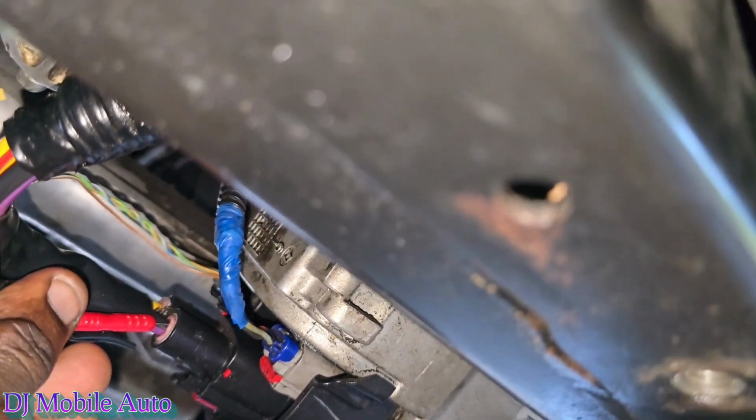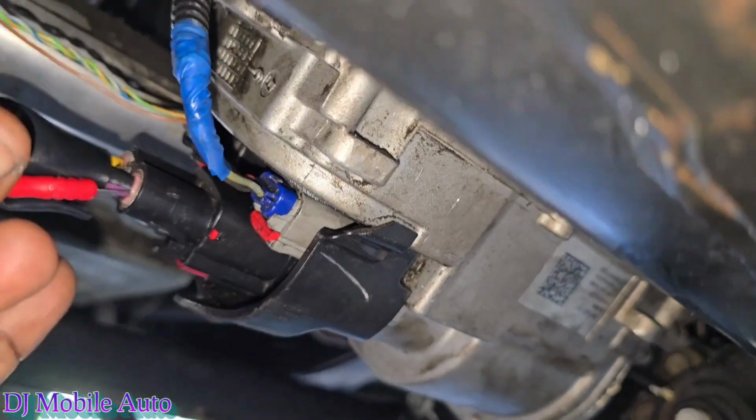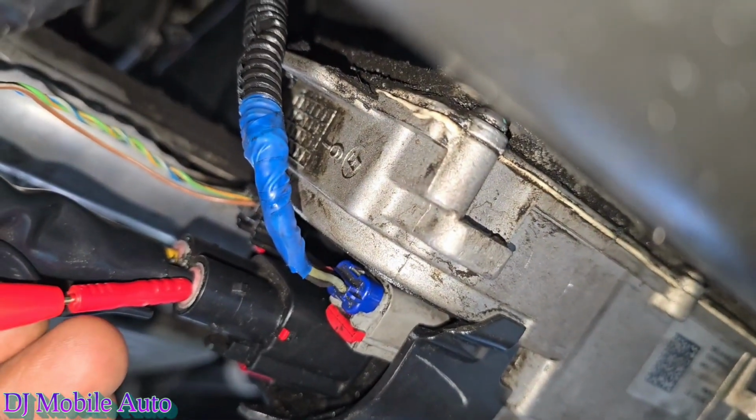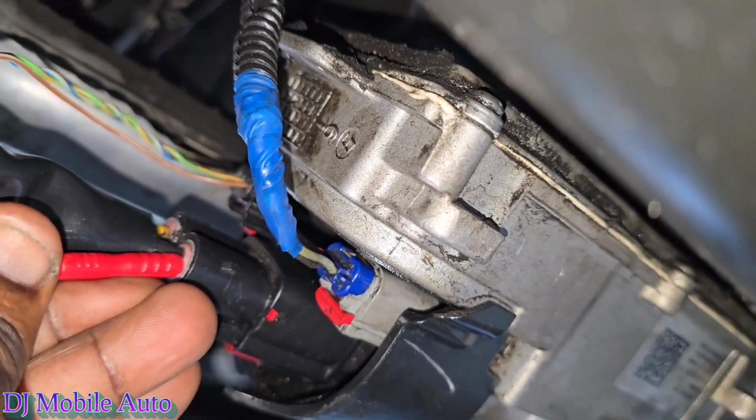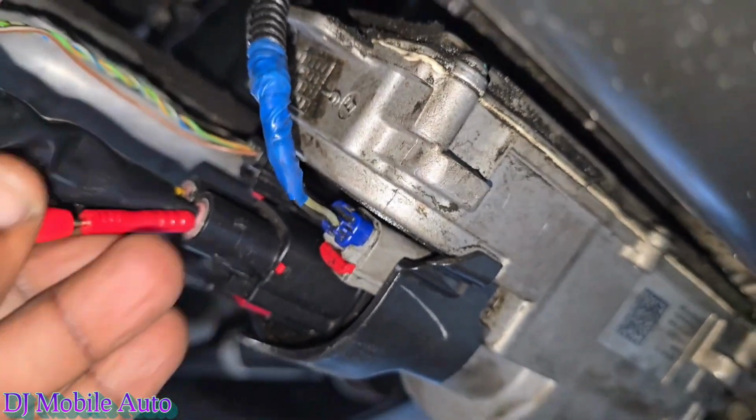That's my ground for the motor. So I'm expecting to see nothing more than, let's say, 100 millivolts. I'm expecting to see ground right here. Alright, so that's a good ground. I'm seeing like 2 millivolts, which is real good, right? So that's coming off for the ground. Is it going where? Probably going somewhere on the body.